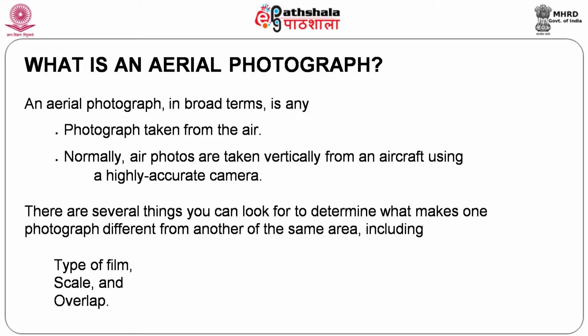As far as photographing is concerned, aerial cameras are fitted into aeroplanes and these cameras will expose at different stations, take a photograph and then send it, or you can also collect the data at a later stage. These are normally taken maintaining verticality. So, very important is that all aerial photographs should have verticality, in the sense the line of sight should be vertical. If you are going to use any kind of aeroplane, obviously aeroplanes are not static objects, isn't it? They are dynamic in nature.